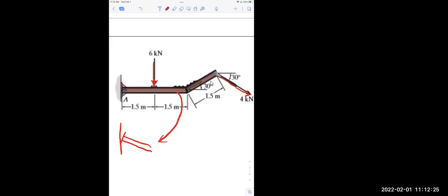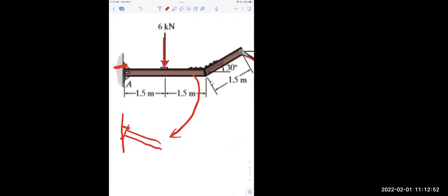In other words, if there was a kind of a bolt on the top of this that was bolted back into the wall, that bolt would want to kind of get pulled out of the wall as a result of this. And so it's actually very interesting to notice that because both of those forces are pulling down, this thing wants to rotate down, or what we would call negatively. And so I actually don't need as many bolts on the bottom of this, because the bottom is just going to kind of stick to the wall all by itself anyway. So I don't really need that much down there, but I might need a whole bunch of extras on the top. So notice it's interesting. You don't just kind of put bolts over there. You got to think about where are they and how much force. And really that's what this calculation is all about.